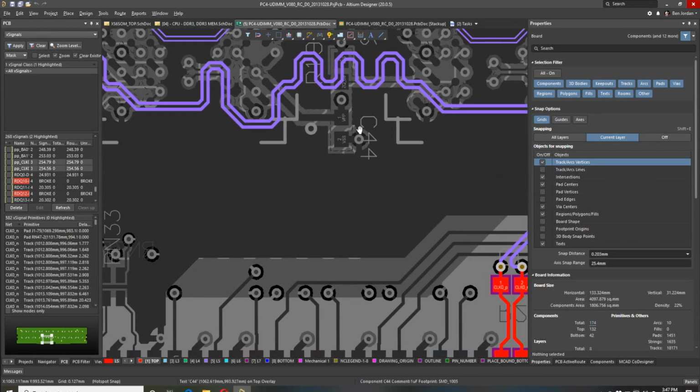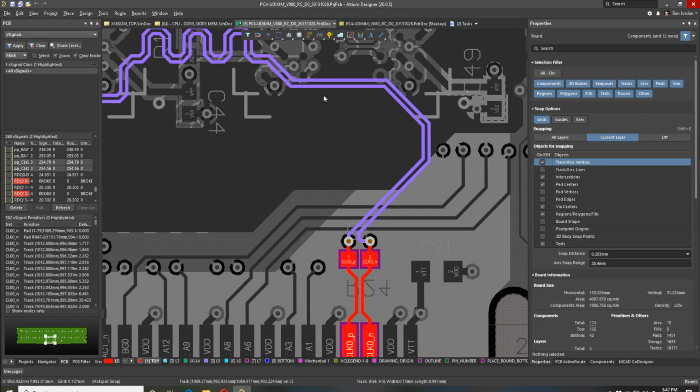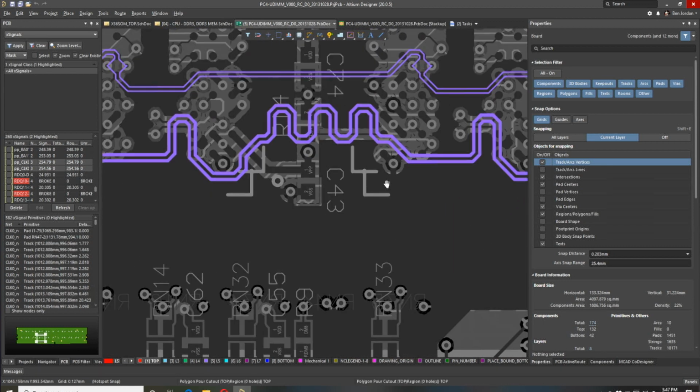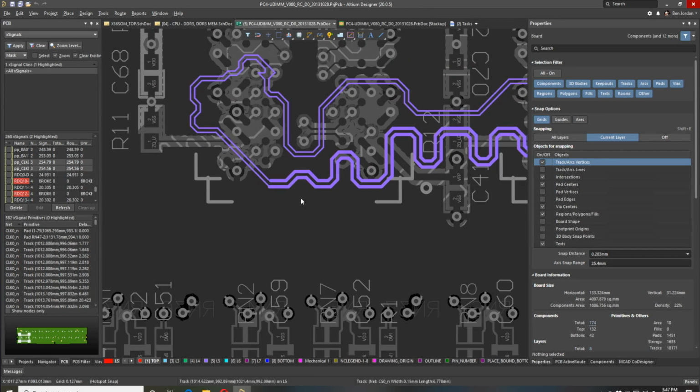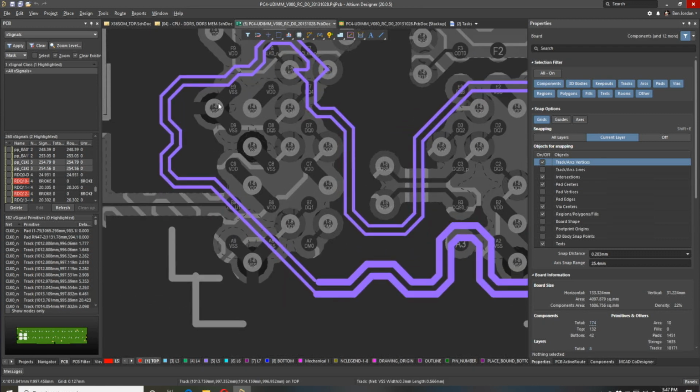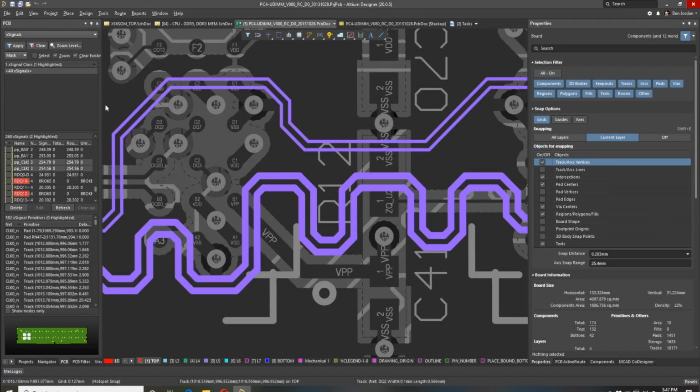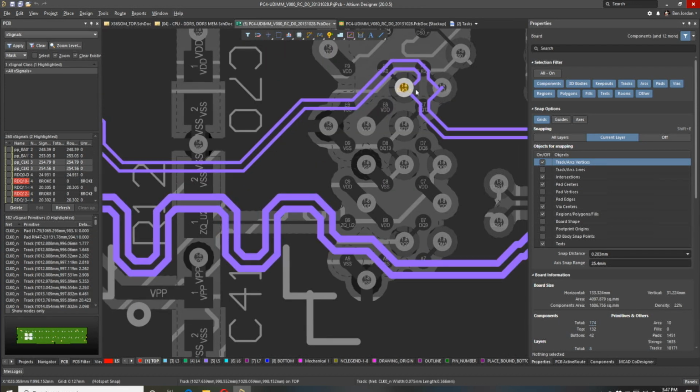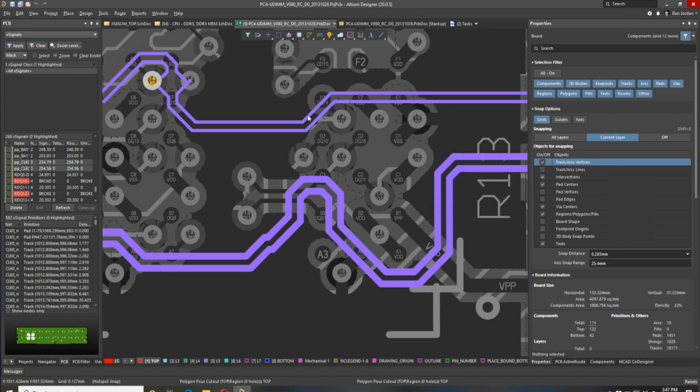And note that on this layer, from the connector, we have a thicker trace width. So it's a lower impedance diff pair until we get right to the end where we're about to actually go through all the chips. And then we're length tuning and phase tuning, one chip to the next, and this is where it connects to the next device. There's devices on the front and the back of the board, so we're connecting to both of them through these vias. So when Susie was talking about short stubs, we're doing what we can here to keep them as short as the via barrel, basically, and no longer.